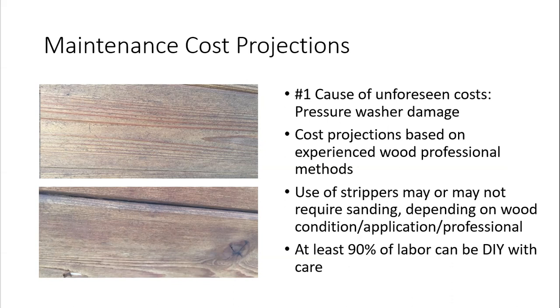Now, when we talk about strippers, there are a few caveats in all of these projections. Again, these are thinking points. The use of strippers may or may not require sanding. It's going to depend on the wood, the application, the professional. Okay, so when we say that your labor increases substantially with strippers, those labor estimates can be pro or not depending on the sanding. Sanding will increase a tremendous amount of labor.